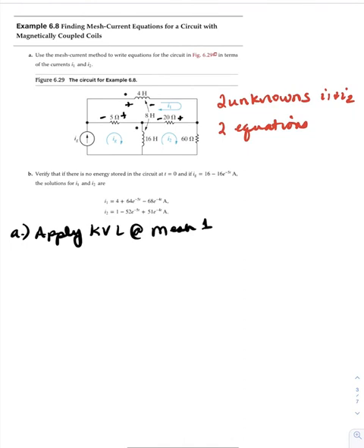All right. As I1 approaches the 5 ohm resistor, there is also the current I sub G going through the 5 ohm resistor. So we set up our voltage drop as I1 minus I sub G. Now we approach our 4 Henry inductor. So it'd be 4 Henrys times the change in current I1 over time. This is our self-inductance.